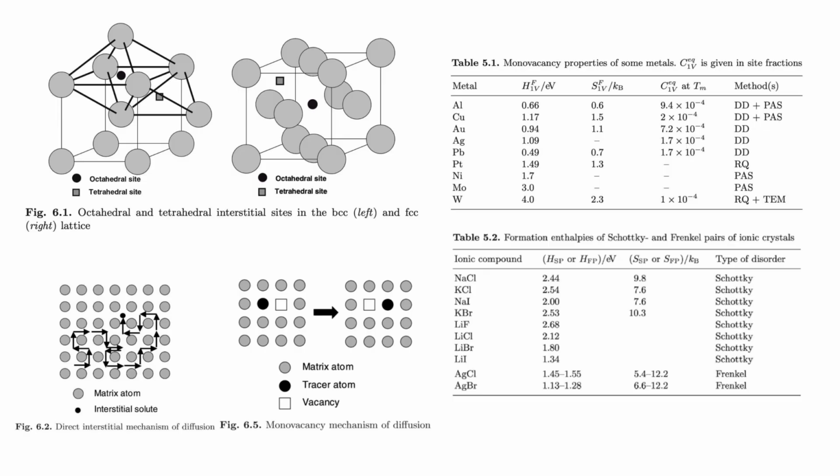We look at both BCC, FCC. We look at their interstitial sites. For each one of them, there's a tetrahedral site, there's an octahedral site. We spend most of the time on FCC. We look at why carbon is more comfortable in the octahedral site, because the bond distance is closer to the equilibrium one, but much shorter in the tetrahedral site. We also looked at when it jumps from one octahedral to another octahedral, which path it's going to take, because that's very relevant to this course. It's about diffusion. Carbon is going to diffuse from one octahedral site to an empty interstitial site. So we did that last time.